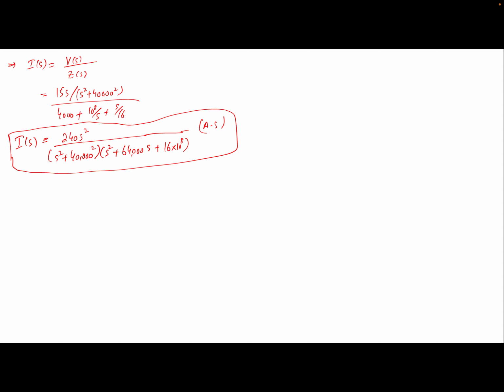And I need to find I of t. I have to take an inverse Laplace transform. Before we do that, sorry, we do an intermediate step where we apply the initial and the final value theorems and see that things are still making sense and our expressions are correct. We implemented this as a sanity check, so we can still do that over here. I'm going to apply first the initial value theorem and then the final value theorem.